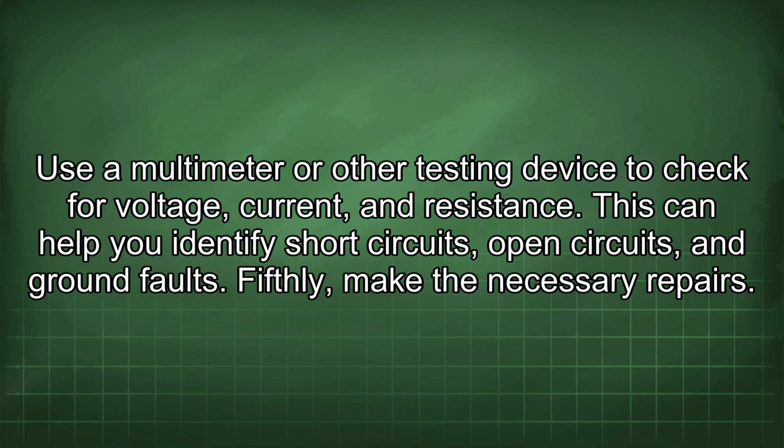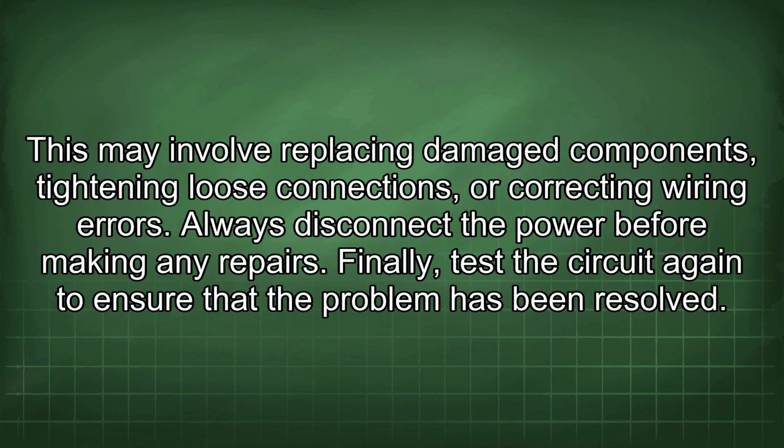Fifthly, make the necessary repairs. This may involve replacing damaged components, tightening loose connections, or correcting wiring errors. Always disconnect the power before making any repairs. Finally, test the circuit again to ensure that the problem has been resolved.